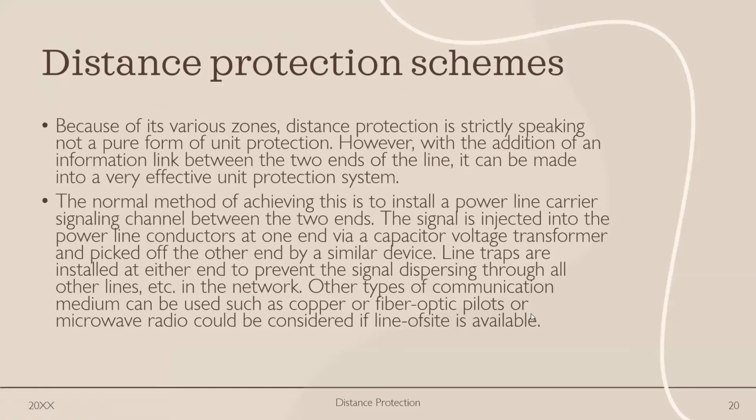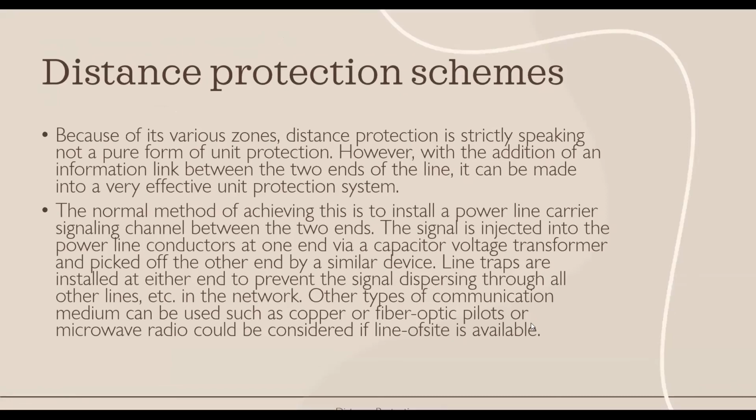Now, distance protection schemes. Because of the various zones, distance protection is strictly speaking not a pure form of unit protection. However, with the addition of an information link between two ends of the line, it can be made into a very effective unit protection system.